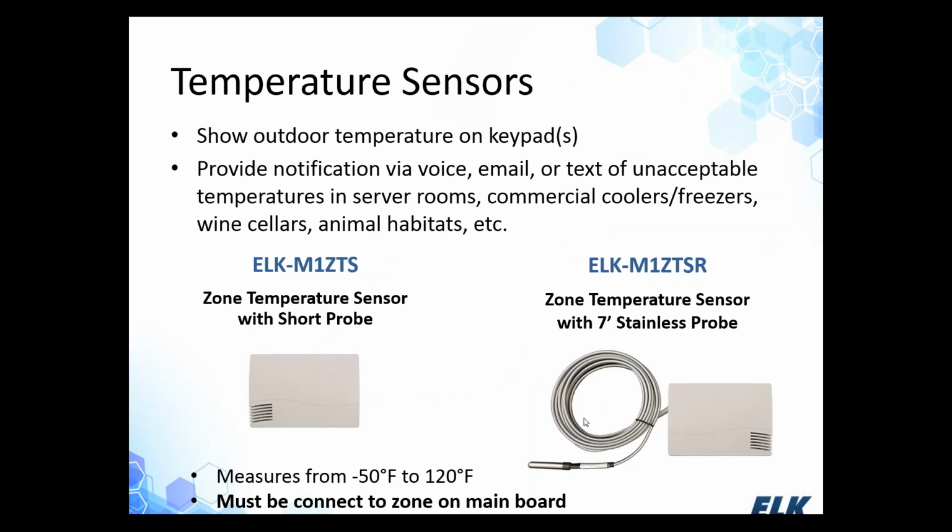All right, now Brad did talk earlier in the presentation about temperature sensors, and how we're able to do this is we offer two different temperature sensors. An ELK M1 ZTS, which basically has the probe inside that plastic case with the venting. We can put those anywhere around that we want to. And we also have one that plugs in that gives you this nice 7-foot long cord with a stainless steel probe at the end. Now you don't want to submerge the whole probe in a solution, but if you're going to put that like in a freezer, you might want to have it in an alcohol solution so the alcohol is not going to freeze, but the temperature is not going to radically change when the door is opened.